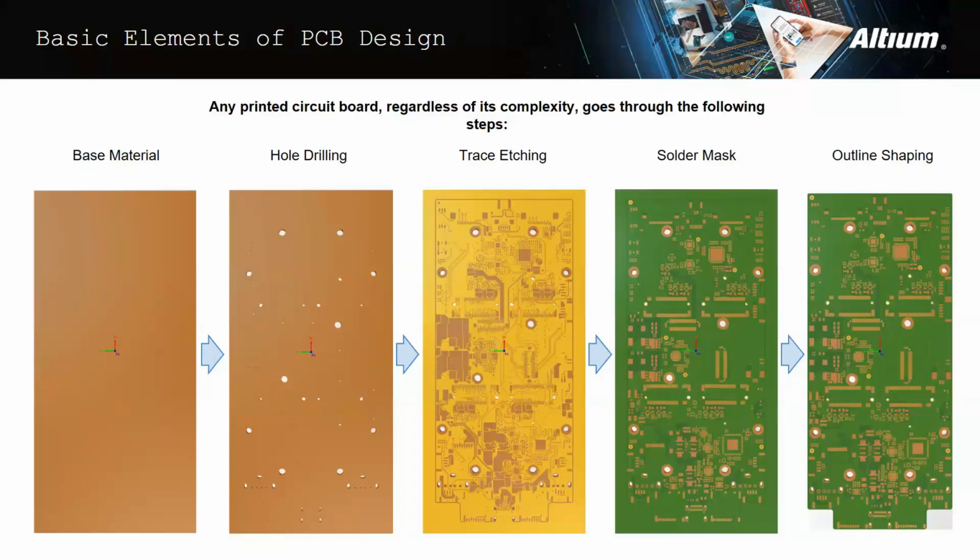This metallization will also bind the layers of the fabricated board together. Along with the drilling, the most important step is trace realization. This is accomplished by etching the copper in an acid process. This step forms tracks and the space between them. After hole drilling, plating, and trace etching, solder mask is applied to the outer surface. This is necessary to ensure that the components on the PCB can be soldered reliably.